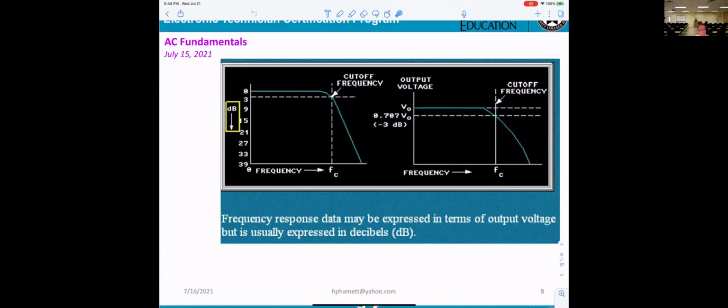Okay, now I'm telling you, they give you two pictures, two outputs. One uses only dB, the other uses numerical values. So what I try to tell you is, this part here and this part here are identical. That means V out and V in are the same, right? You get 10 volt in, you get 10 volt out. That tells you the gain equal to 1.